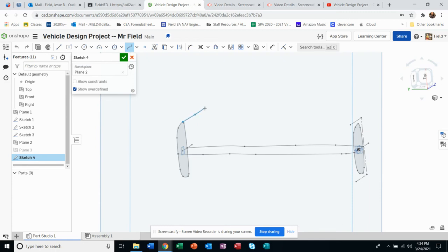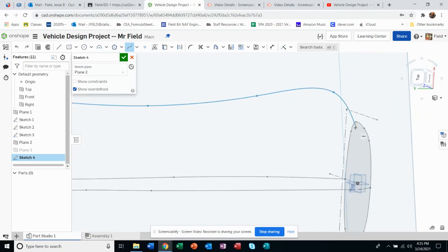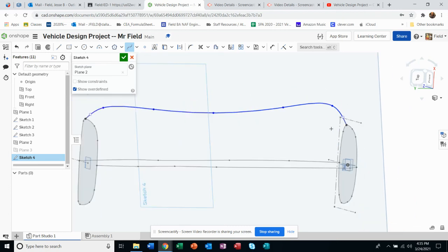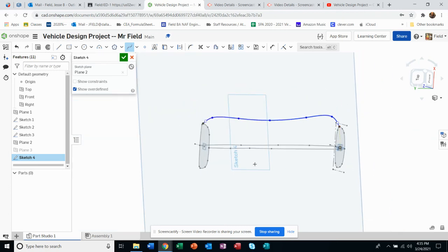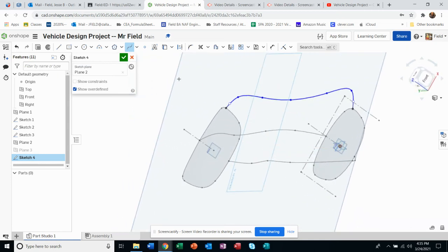All right. You'll see, actually, let me just try and do this. In these cases, I'm going to go with more control points, I think. So I'll do a total of 5 control points instead of the 3 I did for the last one. And then I also got to make sure that goes right there. So I double click. That was, I think, pretty well done. And that's how you have to have it all constructed if you're going to have these control guides work like you want them to, okay?